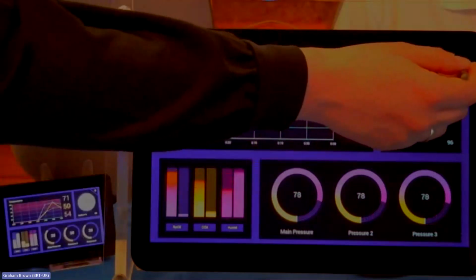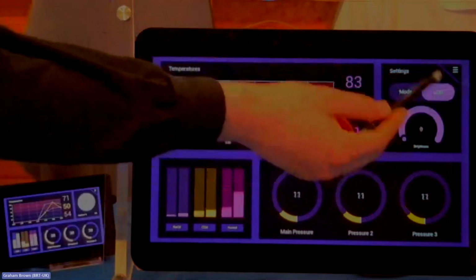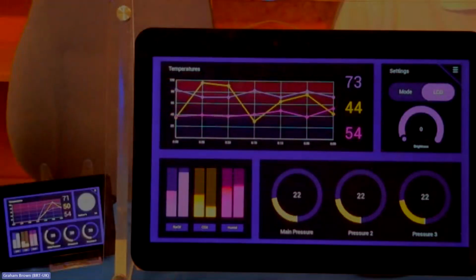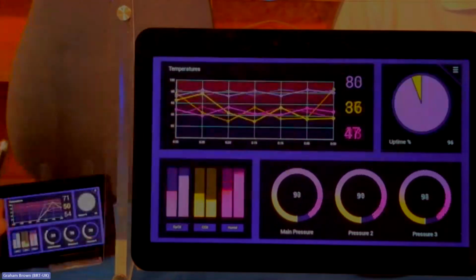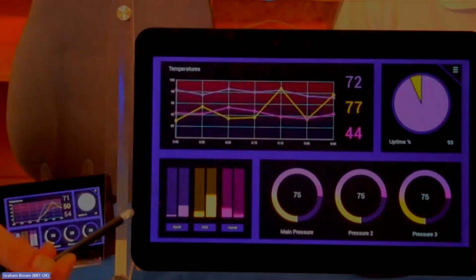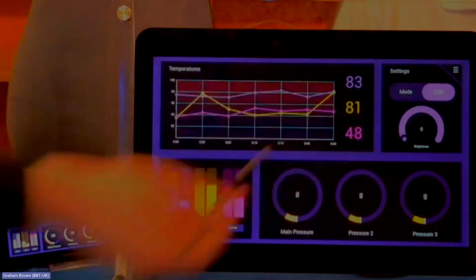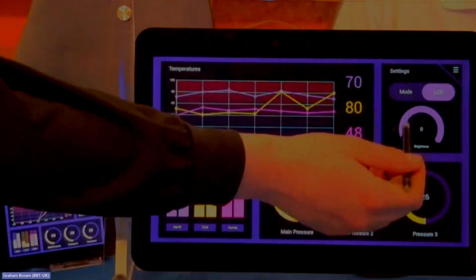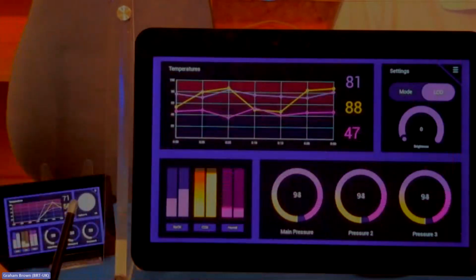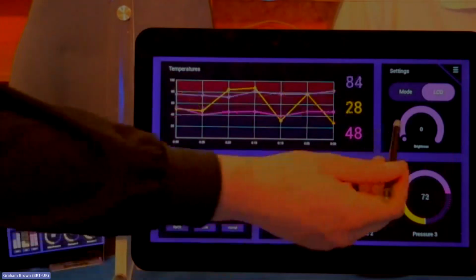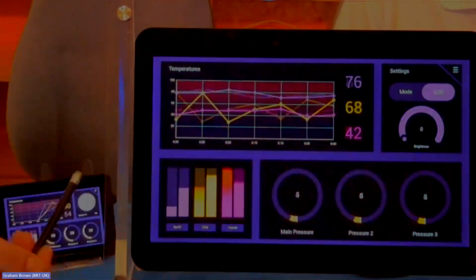So one of them is the touch that Graham's mentioned earlier. And this menu item here has been tagged with a touch tag. And so when we press it, Eve updates a register. The MCU then can read this register and decide what item has been touched. So for example, we can change the sub-menu here based on the tag reported back by Eve. We also have the touch tracking and the arc gauge here for brightness on the screen.